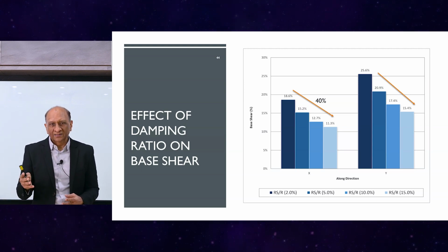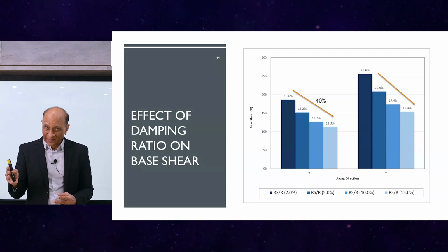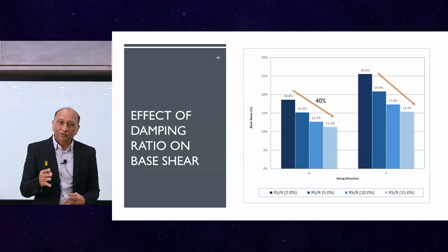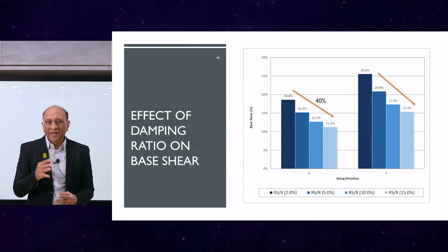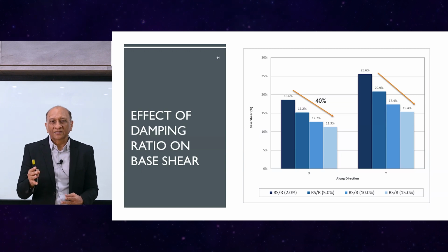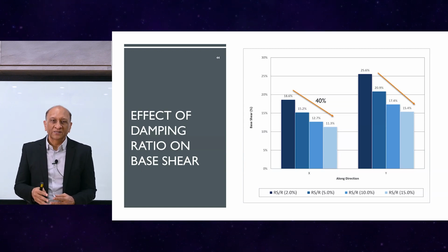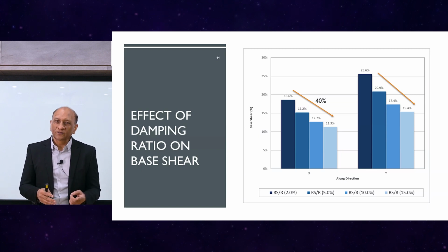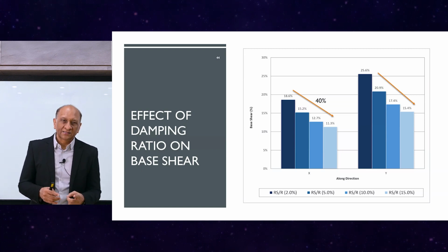It peaks at 2 seconds rather than at 0.1 or 0.2 second like most response spectra. So for Bangkok, the effect of the change of damping and stiffness in buildings up to 20 stories will be negligible because the response spectrum is nearly flat. And this is so different from Manila, where that region will be highly sensitive.